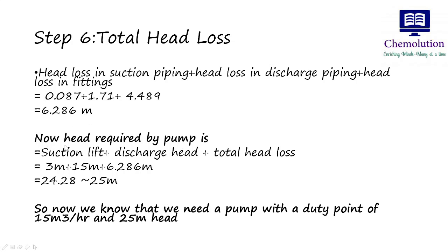Now the head required by the pump, it is suction lift, which we earlier discussed. It is 3 meters. The discharge head where the pump needs to deliver, 15 meter, plus the total head loss. So summation of this will be the head required by the pump, which is calculated as 24.28, which is approximately equal to 25 meters.